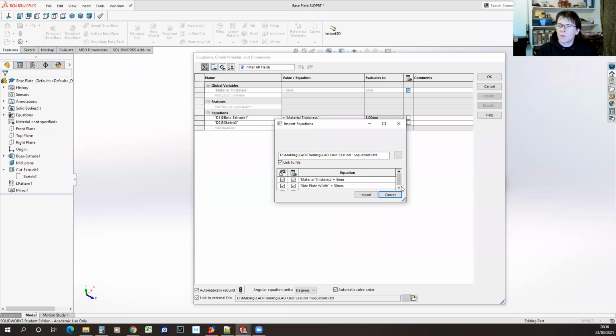So I don't quite understand why SolidWorks creates a mixture of carriage return and carriage return line feeds, or somehow SolidWorks seems to create the file with the carriage return endings, which the Windows editor doesn't support. But if you make everything line feed endings instead, the editor supports those, and SolidWorks is also happy.